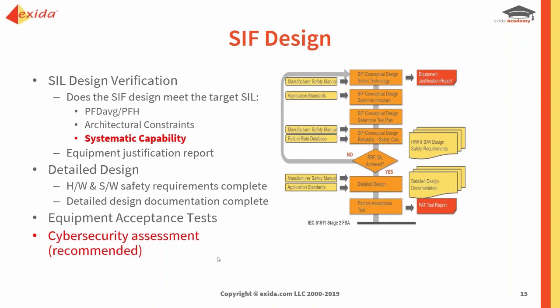Anything that is compromised from a cyber point of view, that is a systematic issue, and that can be the mother of all common cause. Because if you get compromised and you don't know you've been compromised, if the SIS is disabled, so its SIFs, even if the SIFs see a demand, they cannot operate correctly, that's going to have significant consequences, because the SIS and its SIFs are our automatic backup if the BPCS isn't able to contain the problem.